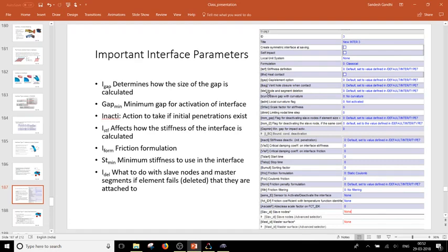Such as iBag, which won't be mentioned in the important features, because iBag is actually more relevant to airbag definitions. Now, airbag is something that is not really part of crash structure, but it is more a part of occupant safety, which is again a crash safety application, but it is a different scenario altogether. So that is where it is more useful. Here, we don't have to really worry about those, so we can keep those 0 or default, whatever it asks for, just to neglect its effect.